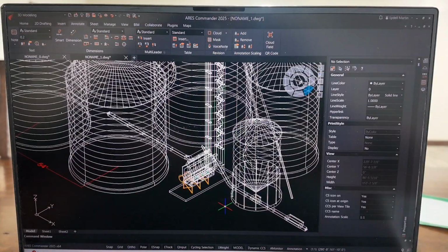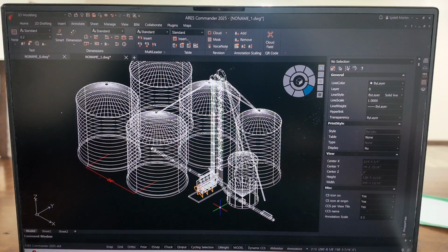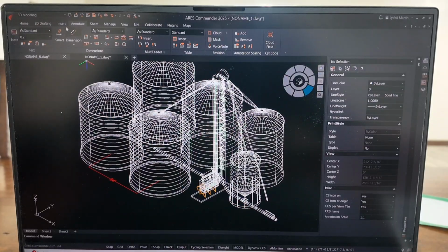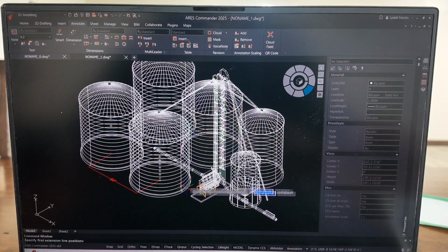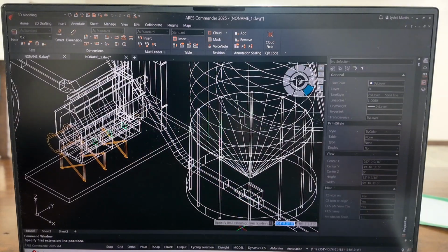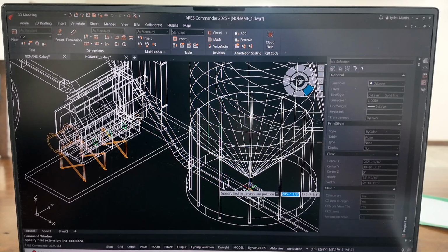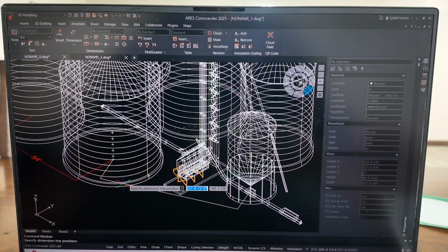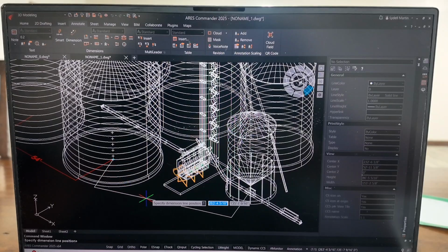So now we're going to go back to the center of this bin. So we're going to go up here, left click on the dimensions again, go down here. When we cross here, we get an X here in the middle. See, when we cross the bottom edge of this concrete pad, we get these 2 X's. You want the bottom one. For the bottom ring of the concrete, we go over here to this bin, go to that bottom X, we drag that out, just outside.